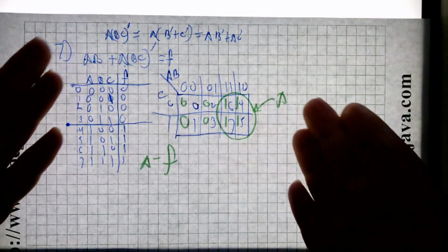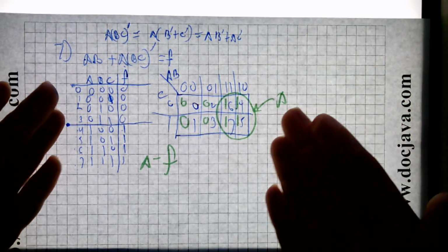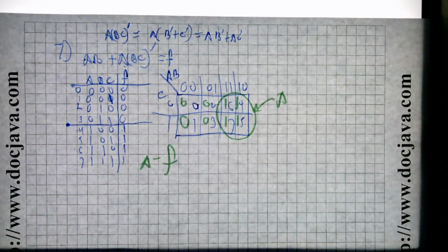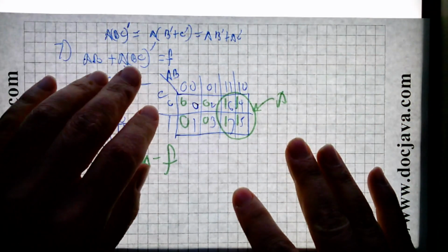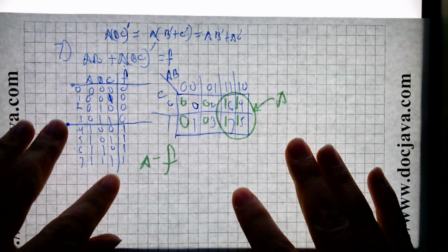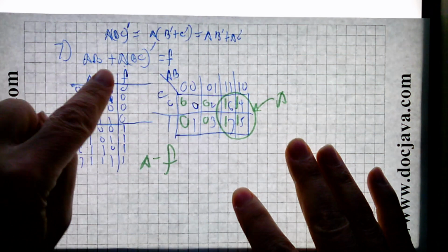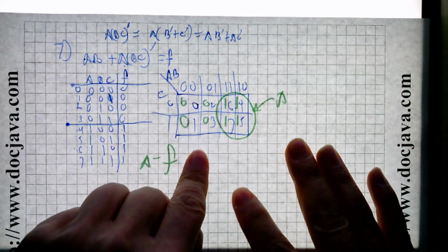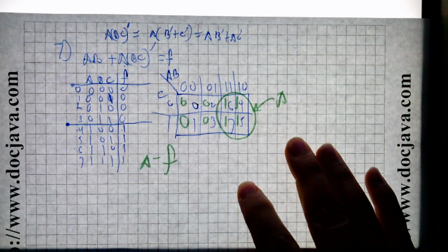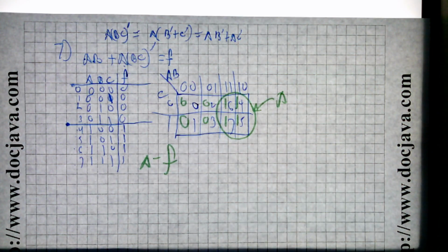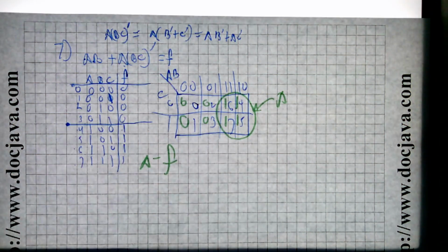And the way I approached it, which was very methodical and correct, you could have skipped steps, done a whole bunch of other stuff. But what I did here, which was really, I think, the right methodically correct thing to do, is figure out where f is going to be true in the truth table, get your K-map, loop your K-map, and that'll give you a minimal form. While here it may have been overkill, that will always work.